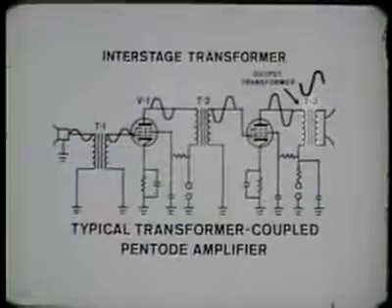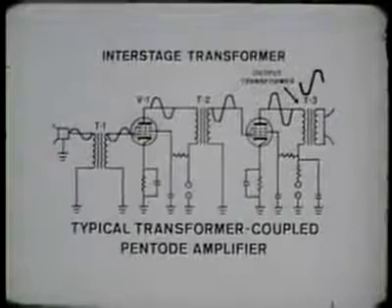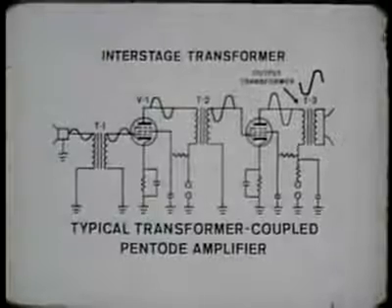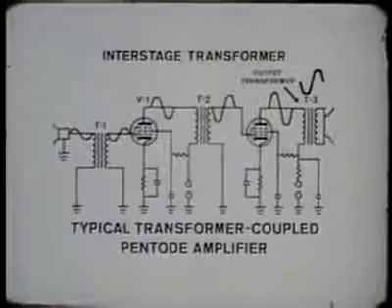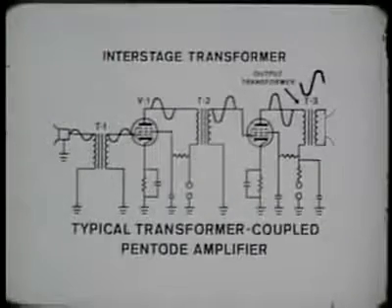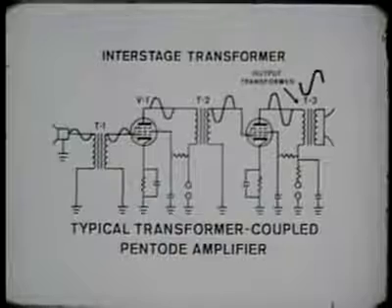Usually an output transformer has a step-down ratio because by reducing the output voltages, the current is increased to the larger values required by the load. It also serves to match the generally high impedance of the power amplifier to the commonly low impedance of the output device.